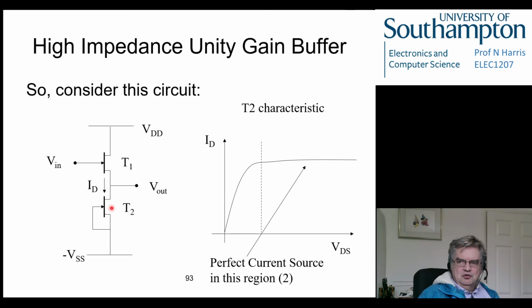They're identical transistors in an ideal world, and therefore this transistor is being told by this one, effectively, give me IDSS, I'm pulling IDSS through me, it's got to come through you. And this transistor is saying, okay, if it's coming through me, then I need to make sure that my VGS is the right value. So it's sort of in reverse. It's saying the current going through here is IDSS, therefore the voltage across here must be the equivalent value of VGS, which is 0. So this one says my VGS is 0, I'm pulling IDSS through myself.